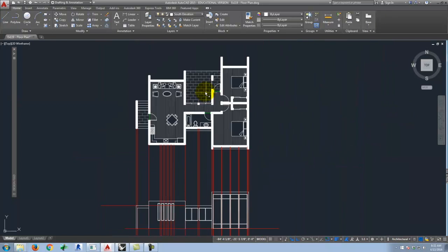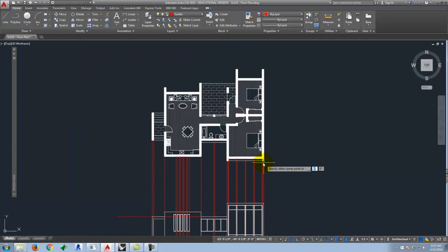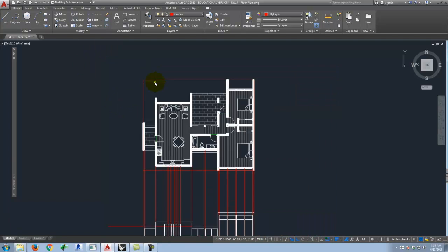So if we look at the floor plan here, what I'm going to do is switch to the guides layer, and I'm going to draw a box, a rectangle, that goes all the way around the outside of my building. And so I'll start at one corner. We'll call it this corner, which is the lowermost right corner. Nothing is below it there. And I need to draw it so that it comes up to this corner, and it lines up with this edge right there and this edge right here. Essentially, this is a bounding box around your object. Okay? So it's a big rectangle, you can see it there, that completely contains my object with no extra space. Does that kind of make sense?